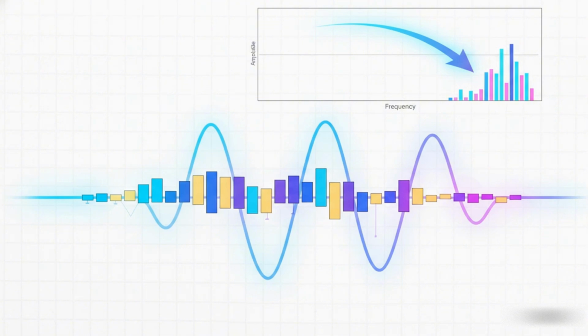And the best part? All those nasty low-frequency harmonics are gone. They've been pushed way, way up the frequency spectrum, all clustered around the high frequency of our triangle wave, where they're incredibly easy to filter out.